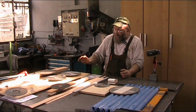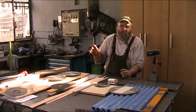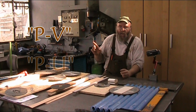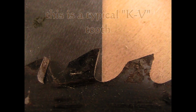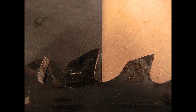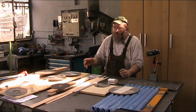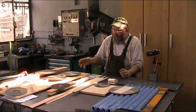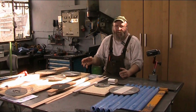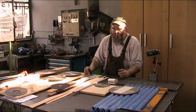Now, for the European market here, we make the distinction of pretty much a KV and a KU, and a PV and a PU tooth. And the reason for that, and I'll show you here when I bring the camera around, is that the K-tooth is more or less a saw primarily for crosscuts. It has a unique tooth geometry. Some people call it wolf's tooth. That's also a common name for it.